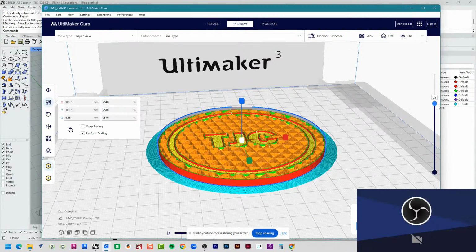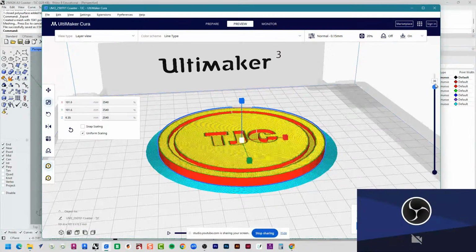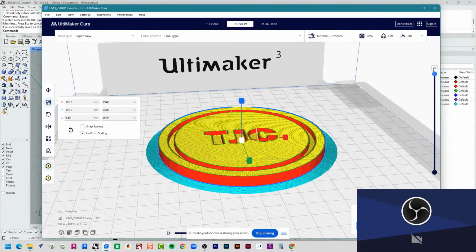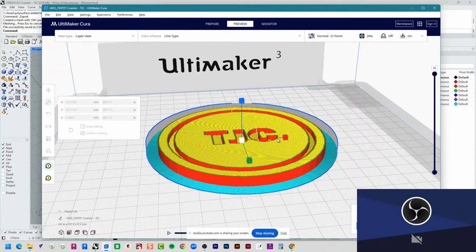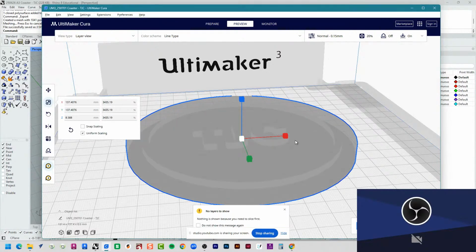All that orange that you're looking at on the screen, that is a diagonal infill pattern. So that way the 3D printer is not just putting plastic everywhere. It's doing it super efficiently where it needs to be. If I scroll this all the way up, I'll see that I have 42 layers. It's going to take 42 layers of 3D printing to create my coaster. And this coaster is very small. Down at the bottom, my estimated amount of time of printing is 3 hours and 52 minutes. So that's actually a lot more than I thought it was. Oops, let's undo that.